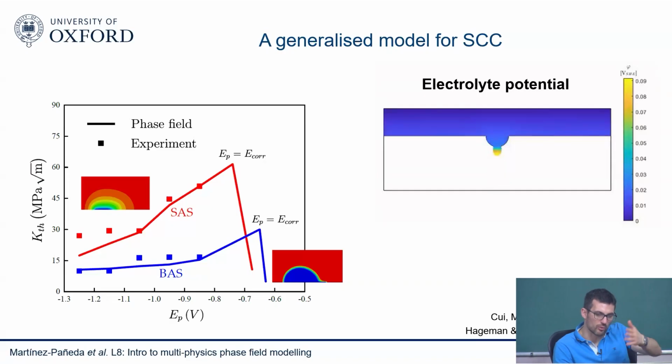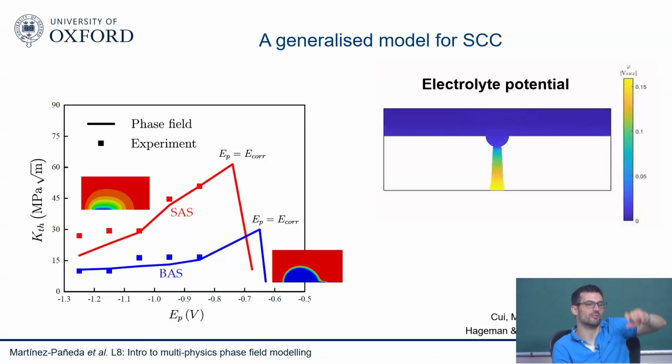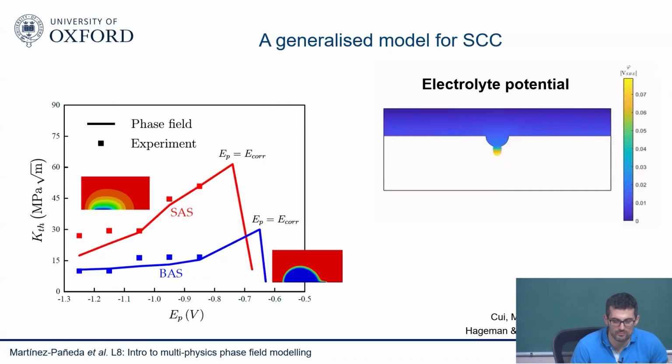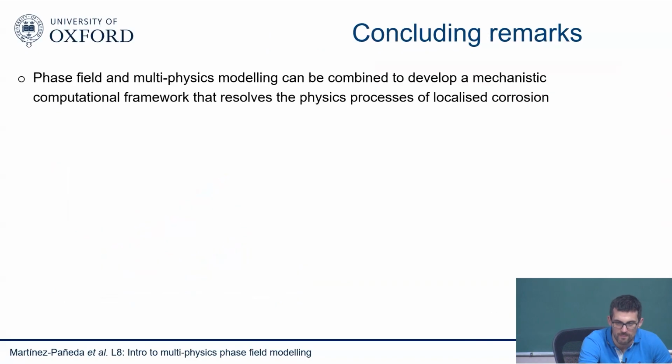This is a problem not only for corrosion, but also, for example, for the hydraulic fracture community, right? They're interested in fluid flow, so they need to know the crack opening. There are multiple ways; the hydraulic fracture community has developed many. Some are very simple: you get a strain field ahead of the crack, from the strain you develop displacements, and from there you interpret the thickness. There are various approaches that different people have taken. We propose in that CMAME paper what I think is a more rigorous treatment. It's still quite complicated, so I don't think the last word has been said on this, but we developed what I believe is a rigorous treatment, including treatment of reactions and electrochemistry and so on. So you can take a look at that one there.